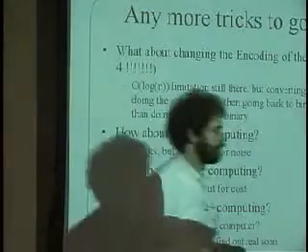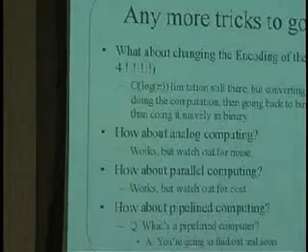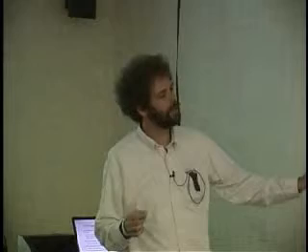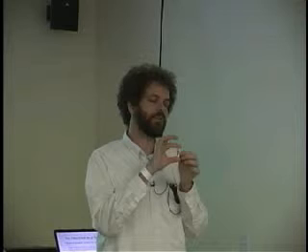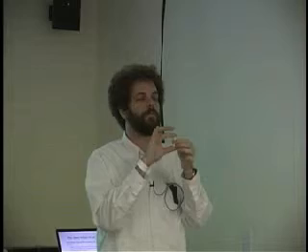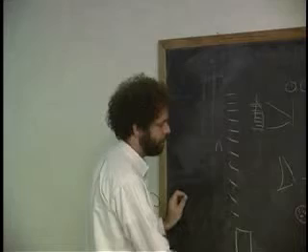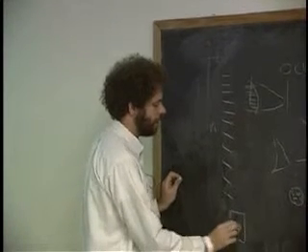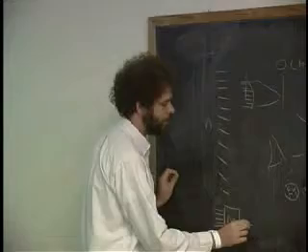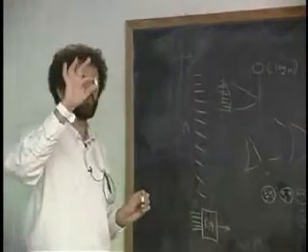There's a nice way to see this. If I wanted to know the length of this piece of chalk summed with the length of this piece of chalk, I have 2 ways to do it. I can measure this piece of chalk and write it out in bits, measure this one and write it out in bits, and add the bits together. Or I can put the 2 of them on top of each other and measure this. This would be an analog computing way of finding the sum of these 2 lengths of chalk. And one scheme that you could use is something called a digital to analog converter, or a D to A, which would take a number of bits in here and produce a voltage out here, which would correspond to how long this piece of chalk is.